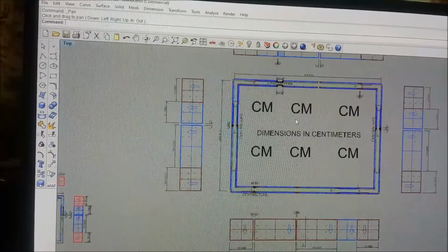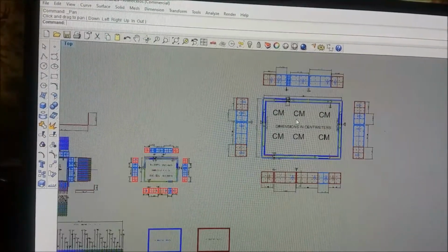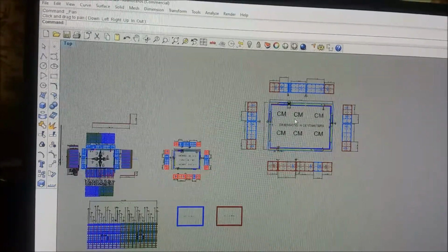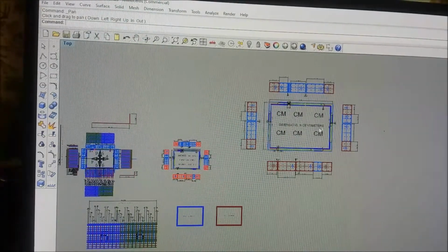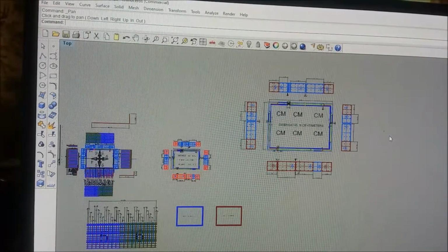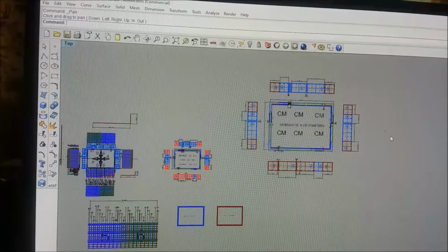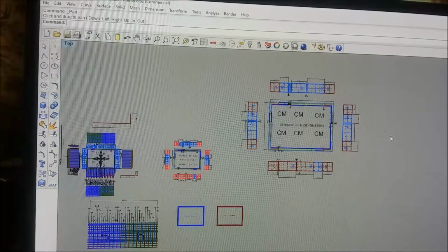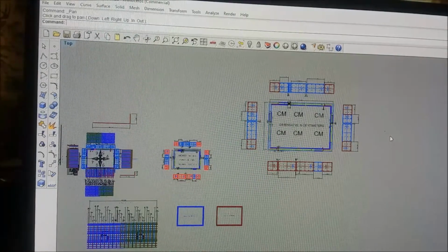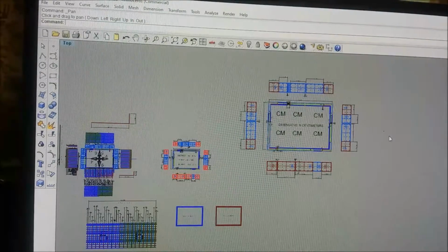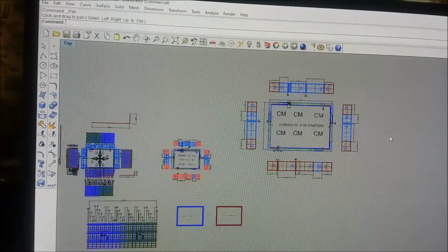Last word of wisdom. You design a house from the top down, because every time you go down a floor, all the stuff above it has to be counted, and it gets heavier and heavier. The strongest part's got to be next to the bottom, because the top tie beam only has the weight of the trusses in the middle roof, and the next one you have to add the wall weights, and then add the floor slab, and then the next tie beams, and then the lower walls. So when you get to the tie beam on the bottom, it's going to be 3 times as big as the one at the top.